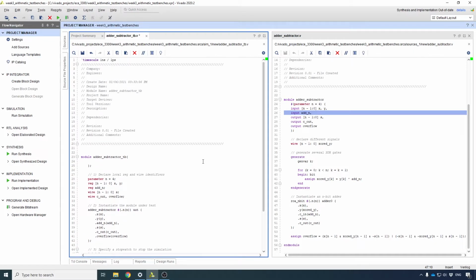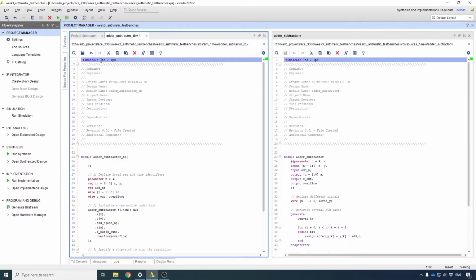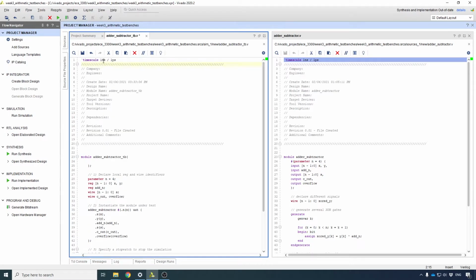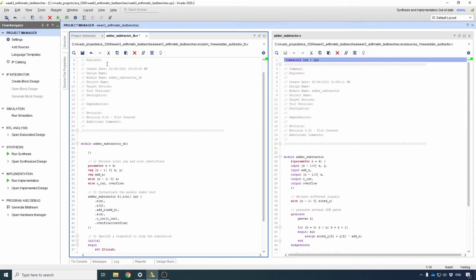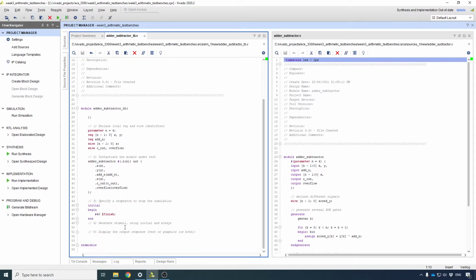All of the Verilog code that we have written so far has this time scale at the very top of the file. This time scale tells me that if you're using that hashtag number, the delay is actually 1 nanosecond. Every one of them is 1 nanosecond. If you change it here and you put 10, for example, it becomes 40 times 10, which is 400 nanoseconds, okay? So I'm just going to keep it at 1 nanosecond, and that's it.